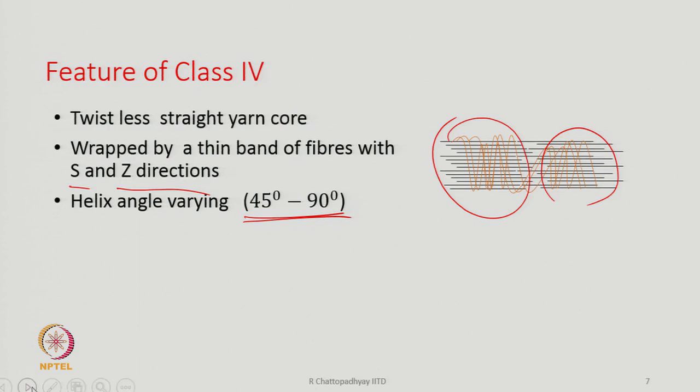So, this disturbance could be there in the wrapping, because of the possibility of air turbulence within the jets where high pressurized air is injected. So, within the jets or within the nozzles, we can say that a lot of disturbance will be created by the vortex, and because of this the wrapping sometimes may not be very uniform.